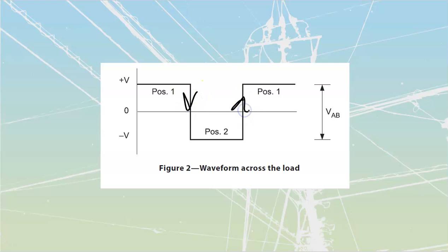Hard edges are always hard on our AC, right? It's dV over dt, really, when you take a look at it, right? Change in voltage over top of change in time, that is going to be quite significant, and that can be a bit of a problem for anything that's going to be electronic. It's also a problem for anything that's magnetic because we're going to have rapid changes in the amount of current that we're going to be forcing through stuff.